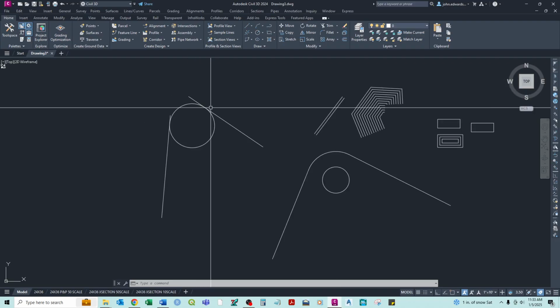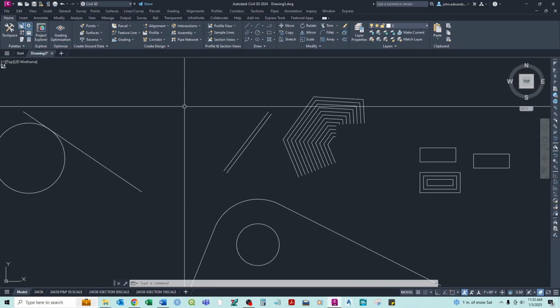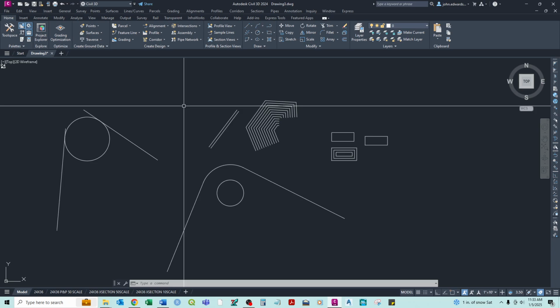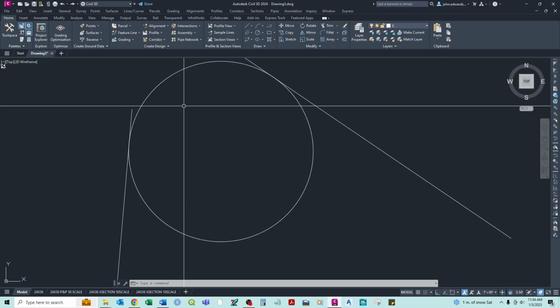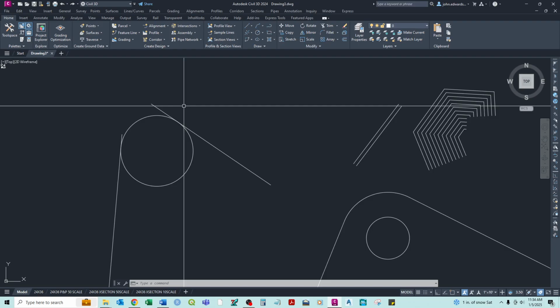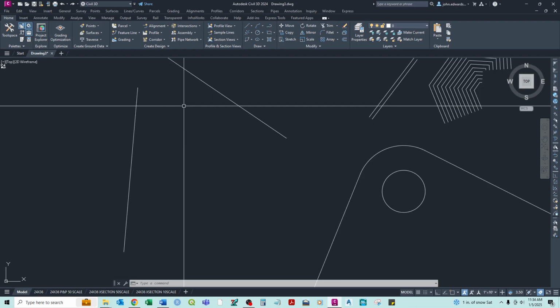every time you move, you pan, or you zoom in and out, because if you remember the video where I talked about zooming and panning as actual tools, AutoCAD sees that as an actual tool that you use. So if you hit Control Z to undo, it undoes the pan, it undoes the zoom before it undoes actual functions. Whereas a lot of programs don't consider zooming in and out, or panning around, as part of an actual function that it needs to undo.